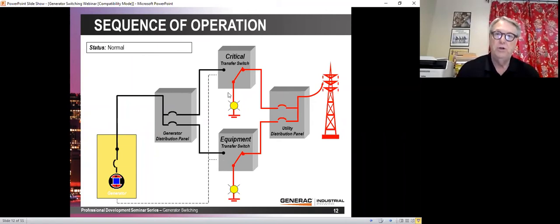The 2-wire start works just great. You just parallel the wires. So if either one of those switches closes its contact, then it will start the generator. So you may have one switch that for some reason loses power and the other switch doesn't. That generator will still start.